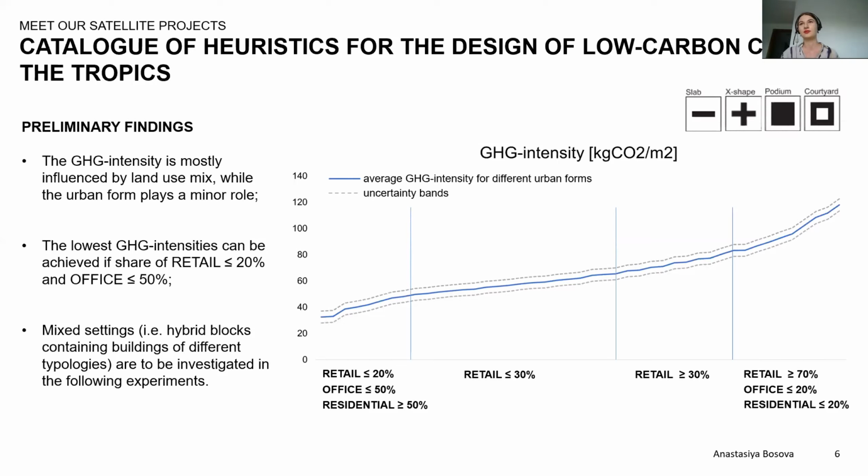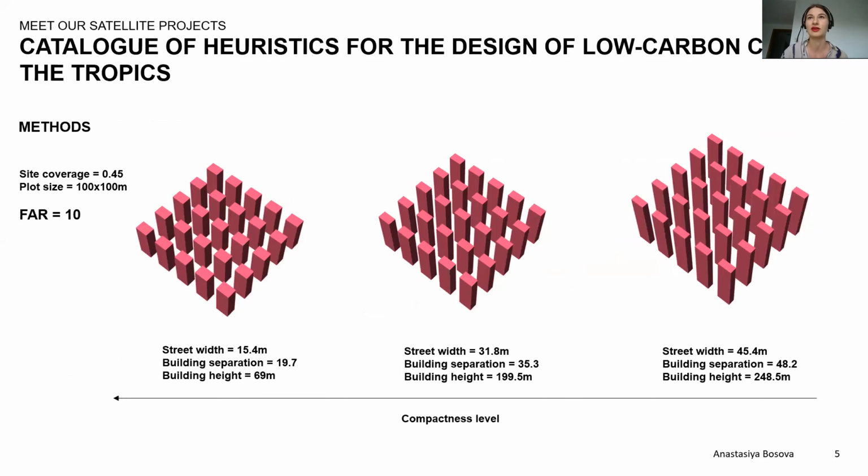I think that it's very important to keep in mind how the district that I analyzed looks, and this is mostly a homogeneous setting. If the buildings of those typologies are placed into heterogeneous settings, the results will be very much different due to the difference in solar radiation, because the shadings will be different from the different angles given different heights in the urban context. And this is one point.